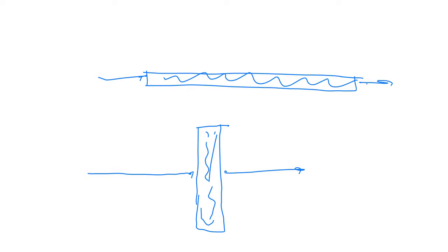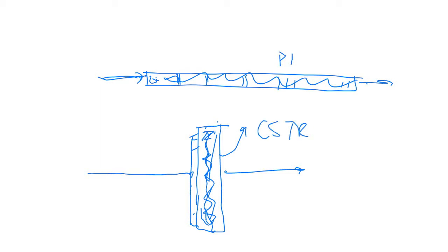Chances are that if you have it here, even if I just allow it to flow in and I've got packing, it's going to be nicely distributed and it will be able to in fact flow in plugs through my reactor. But in order to distribute my fluid in a fat reactor like that, I will need some form of a distribution system, and it's going to have a mixing effect. And so in this fat reactor, this will rather behave like a CSTR than a plug flow reactor.